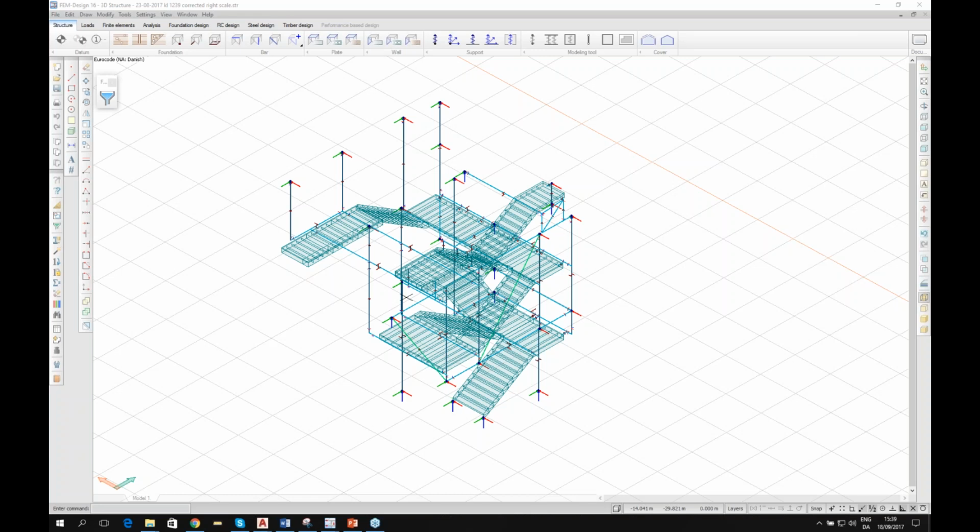Ideal mesh size, that's a good question. The best way you can do this is to see when your results converge. Normally, I would say that the mesh FEM-Design gives is a very good first guess. But if you want to be sure, you need to look at your internal forces and decrease your mesh size, increase the number of finite elements, and see if the values converge, or if they change a lot. In steel, if you have joints, I would go much smaller mesh.